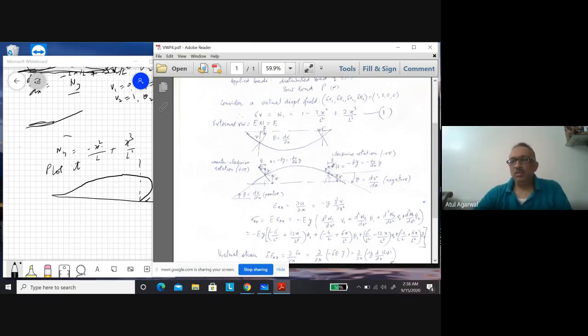And this is the initial position of that plane, this is the final position of the plane as the beam deflects. So you see rotation here is theta clockwise. Here rotation is counterclockwise theta. This theta is positive, this theta is negative because clockwise rotation is considered negative here. Now what is the displacement of a point on the cross section?